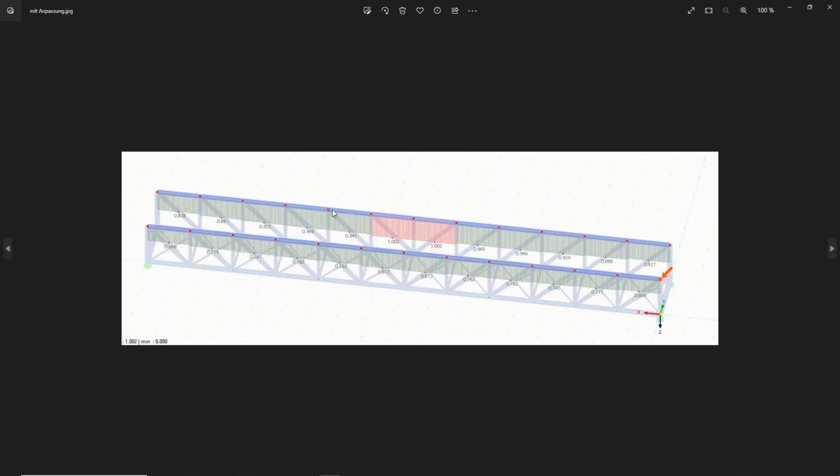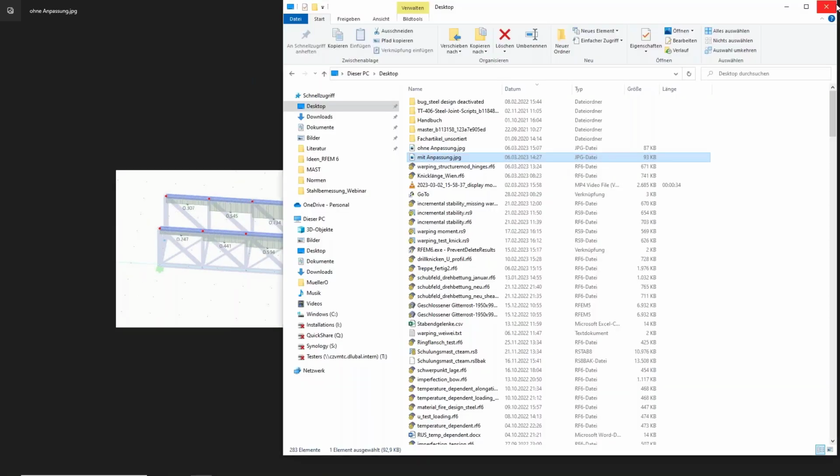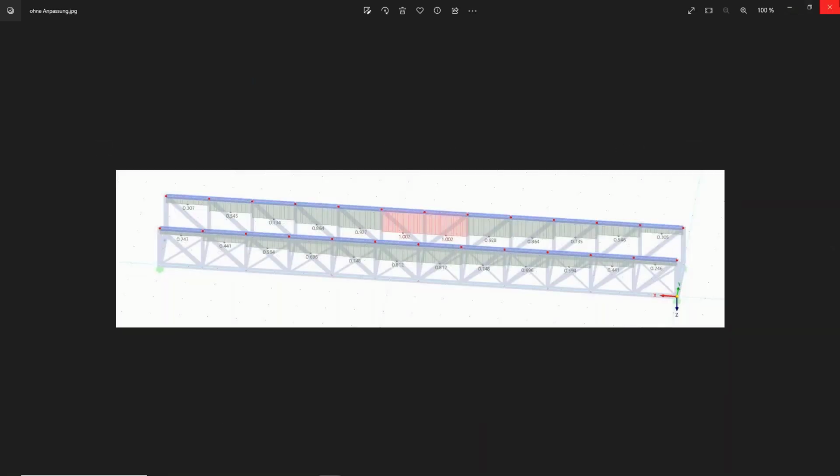If I always use the corresponding buckling length, then it would be a smoother distribution. Now I am a bit on the unsafe side for the outer members, but the most governing design check is in the middle, and I use the same cross section for the whole member, which is also the basis for the equivalent member method. So in my case it is okay to just use this effective length from the member with the highest compression force. Okay, so now I use it here.